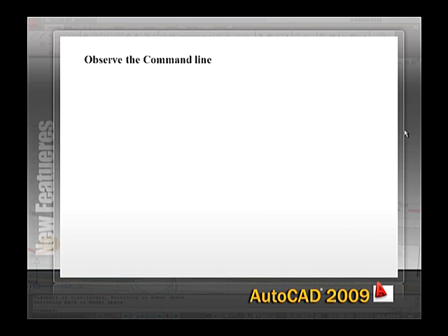When you click on a toolbar command button or a menu choice, AutoCAD types the name of the command automatically and displays it in the command line. If you're watching the command line, you'll absorb the command names more or less naturally. When AutoCAD types commands automatically in response to your toolbar and menu clicks, it usually adds 1 or 2 extra characters in front of the command name. AutoCAD usually puts an underscore in front of the command name, for example, _line instead of line.